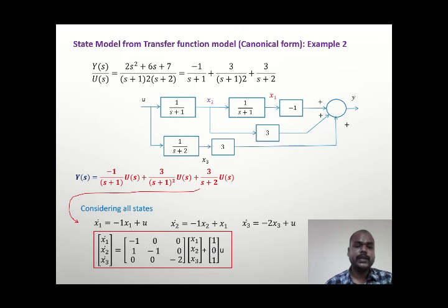Finally, when we do this separation, we obtain our state equations 1, 2 and 3, and put them here. We can have this form of equation here, in which now we don't have a diagonal matrix, and this has a special name, which is called the Jordan block. So Jordan block is a sub block in the canonical form of the state space representation, and generally this type of state space representation is called Jordan canonical.